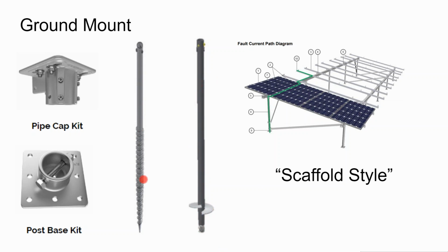You use a ground screw for rocky terrain and an earth screw for more sandy and clayey soils. And that can eliminate the necessity of concrete on the system. So they are a little bit more expensive. You're not going to save any money compared to augering out a hole and pouring in concrete. It comes out to be about the same. But you do save on the logistics of the concrete, and some people think concrete's bad for the environment, so doing solar, it's worth thinking about.